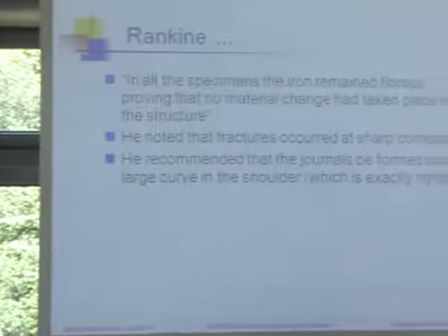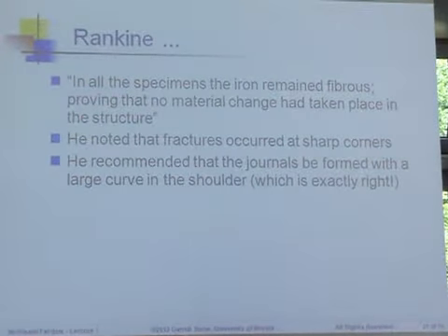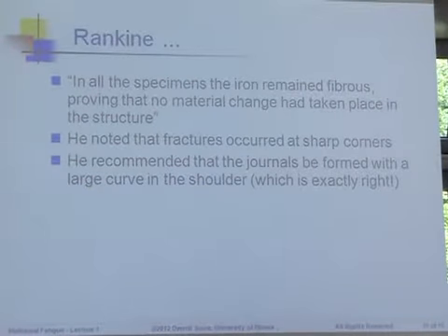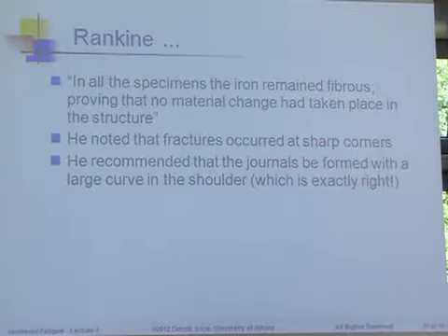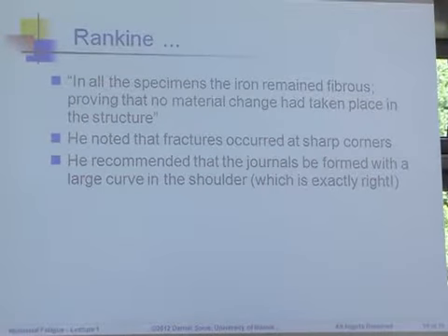And that's exactly what he did. So he looked and said, oh, there are no changes in the material. And then he said, the fracture always occurs at the sharp corner of that journal. He said, just make it bigger and we'll be okay. 50 years before the concepts of stress concentration. 50 years.